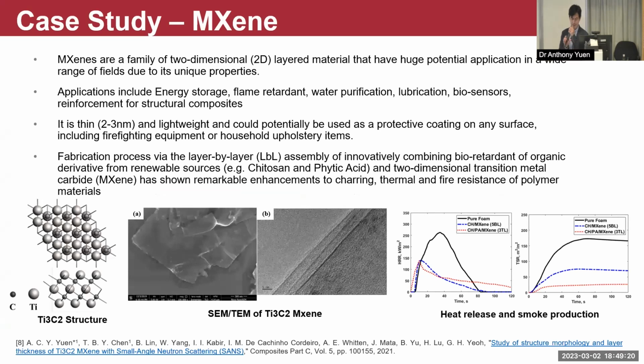One of the strengths of our training center is the development of 2D material. And here we present the Ti3C2 nanosheet. We can even go as far as the STEM image to show that it's actually less than 1 nanometer, almost 1 nanometer thick. So that's why it is super effective. Because this nanosheet, not only can it be a very thin protective layer, it can disperse heat away when there's heat penetration. So you can see it's one of the better materials.